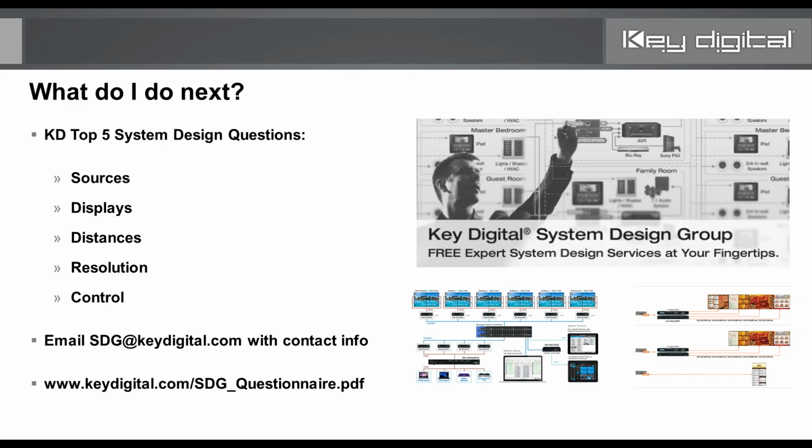The displays: how many, and what are the distances to each, so we can make sure to specify the maximum length extender if needed. Resolution, as mentioned, 1080p or 4K, 18G or 10G, and control by a third-party system, or by KeyDigital's free control app, or by our Compass control system where we could integrate third-party devices as well. That's pretty much all we need.